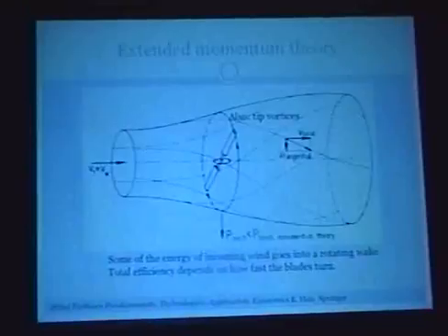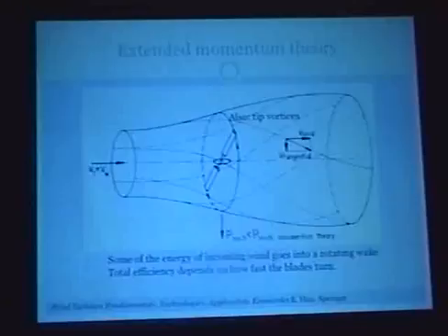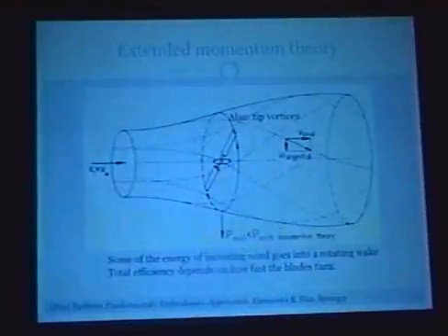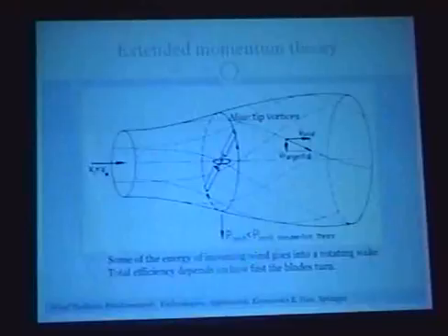So the Betz limit that I described just has to do with momentum conservation, but you also know that you have to conserve angular momentum. So in particular, if you have some stream of wind flowing at your turbine, and it's causing the turbine to spin, then there's some angular momentum being exchanged, and to conserve it, that means that the wake has to have some spin, and to do that takes some energy or some power. So the amount of power that a rotating turbine can extract is less than what you would calculate from just the point of view of momentum conservation.